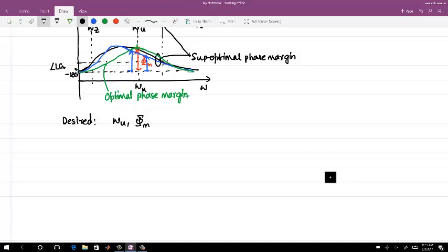The parameters which you need to find in terms of R, C1 and C2 are your omega Z, omega P3 and your ICP. Okay. The other parameters like KVCO, this is the characteristics of the voltage controlled oscillator or current controlled oscillator, and you can have a certain gain on the oscillator, right?